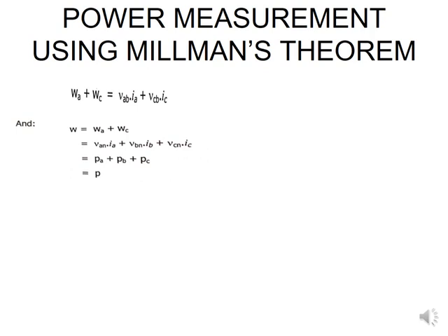which would then, if you had to simplify it, your VAN will still be your normal phase voltage, your VBN and your VCN. They are not replaced by the voltages that you find on Millman's, which is your VAS, VBS, and VCS. Instead, your line currents, IA, IB, IC, are what you are going to utilize when you calculate your power, which you now got from Millman's theorem.